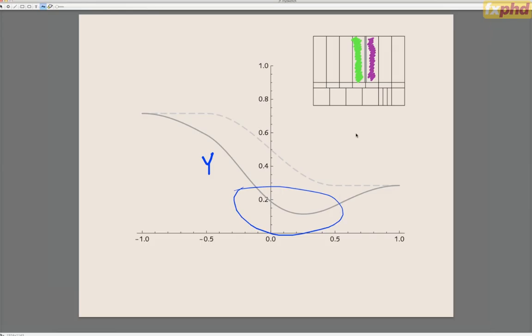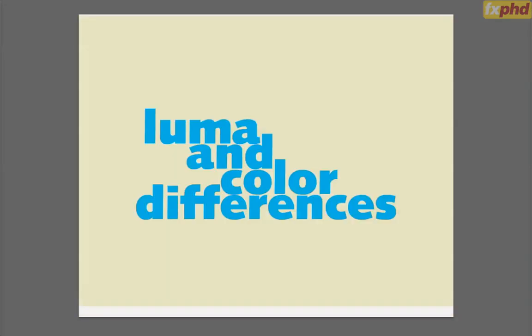So this is the only downside to going into a YCbCr 422 space. And there's other flavors which you'll learn about in a moment, like 420. So this departure from color science theory causes very, very, very subtle image artifacts which almost nobody notices. So in the video domain, we do it all the time, and we almost never get caught. Now, having said that, let's go and do some details.